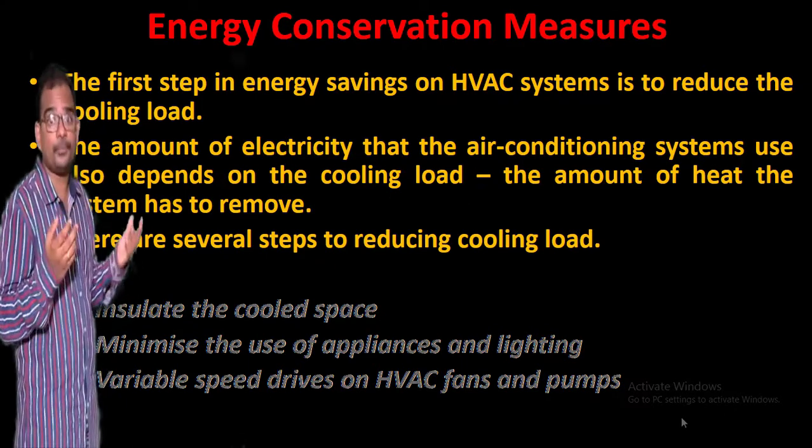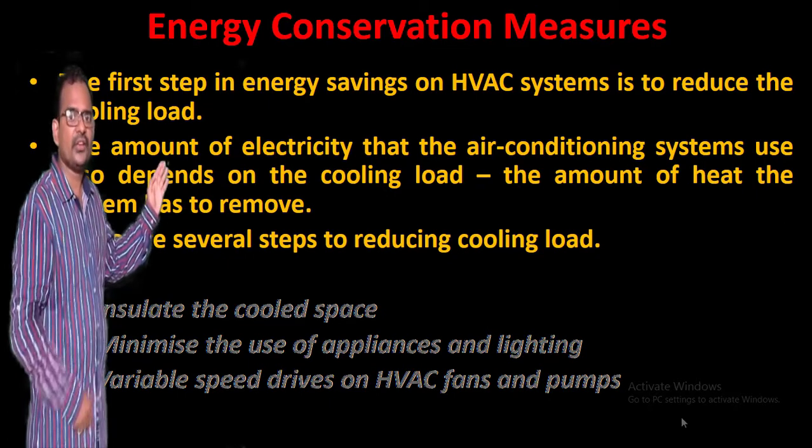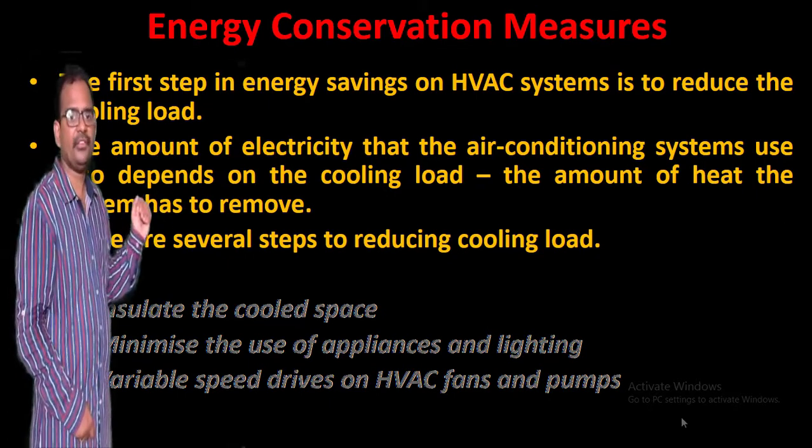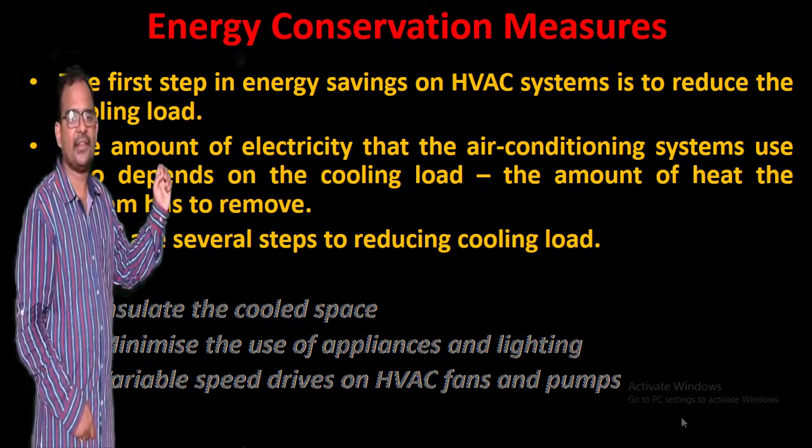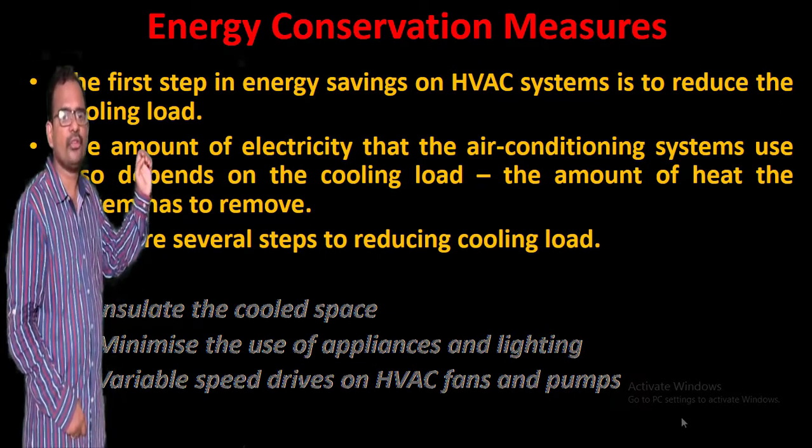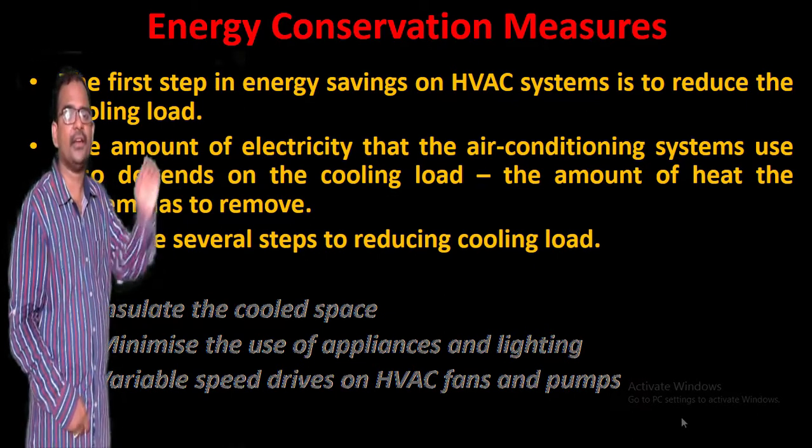So there are several steps to reduce the cooling load. The first one is to insulate the cool space. The second one is to minimize the use of appliances and lighting. And then use variable speed drives on HVAC fans and pumps.